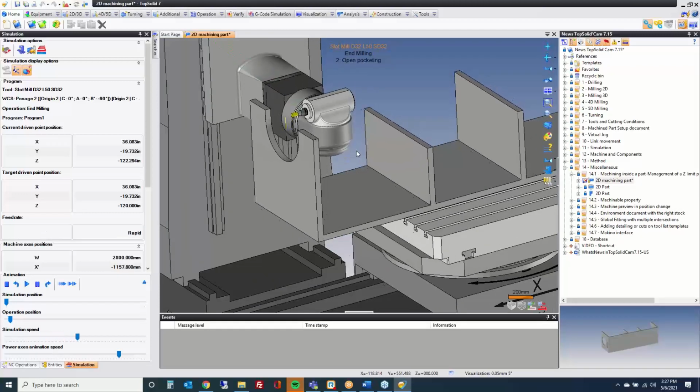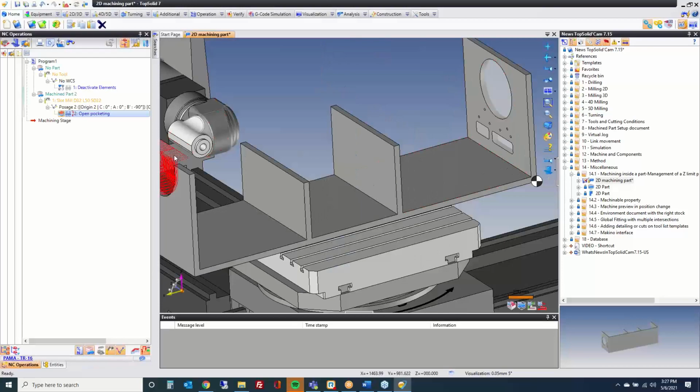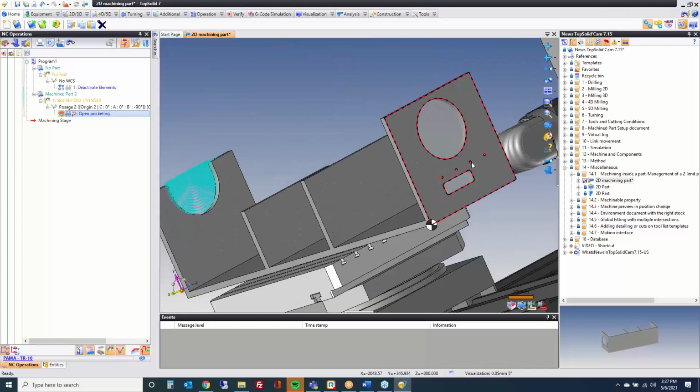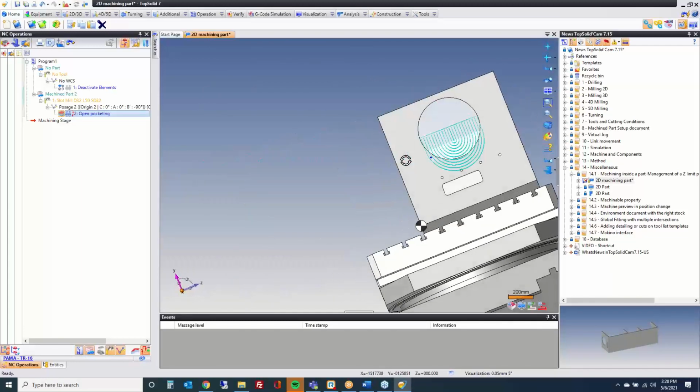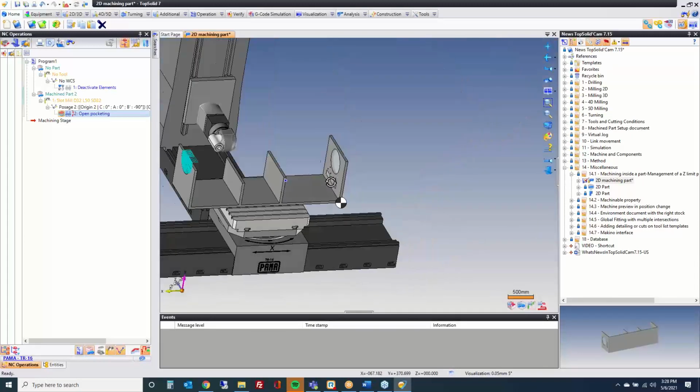Off we go, right? Now, the problem is when you go to do a machining on a weldment like this, remember, TopSolid looks to the highest altitude in that direction of machining, so it sees everything over here. So it makes or sees many intersections or things like that.